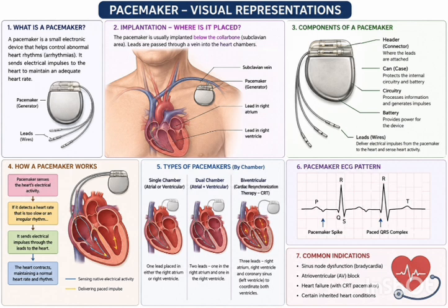Then the construction of a pacemaker. The construction starts with a titanium casing. The titanium casing protects the electronic components from body fluids. Then the battery supplies long-term energy. Then the control circuit does pacing and sensing. Then the leads deliver the electrical impulses. Finally, the electrodes remain in contact with the heart tissues.